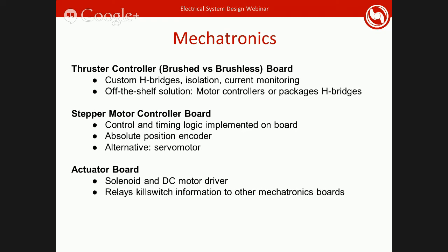There are a lot of great off-the-shelf solutions for motor controllers, and don't feel like you have to implement it yourself. What we like is that by making it custom, we're allowed to choose the amount of current that we can provide, and you can swap out certain components without replacing the entire chip. It's not cheaper per se, but it is more customizable. And it also gives us the high current specs that we need.